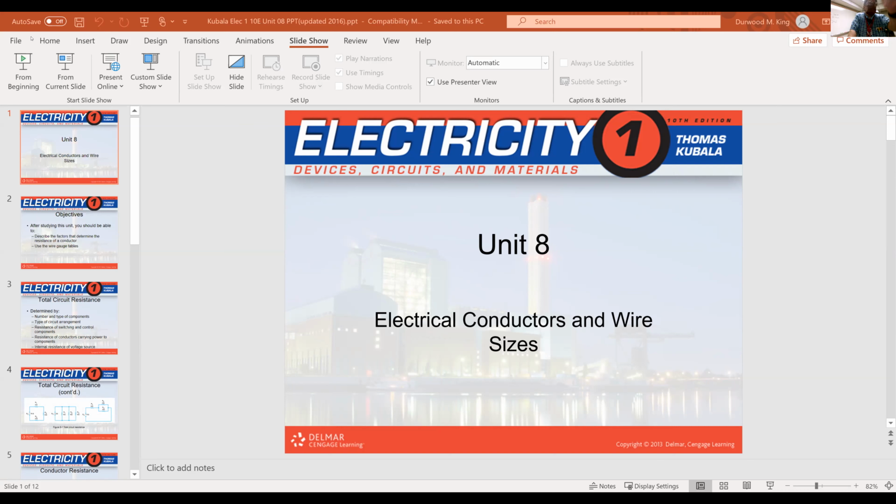You can have a wall switch over there that after a lot of years, it builds up more resistance from arcing, and it can actually produce dim lights because of too much resistance in a switching component. So you can have problems sometimes because of a switching device that's actually got a lot of buildup from arcing and all, and it's pitted contacts. So that's where that third one can come in.